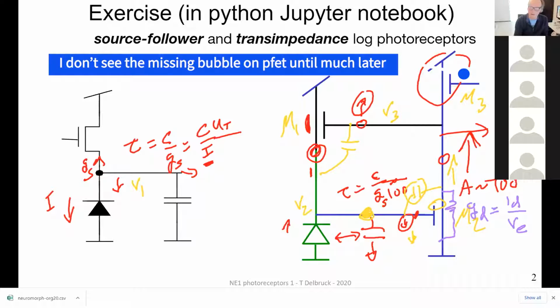I can. Okay. So you have a perfect current source on the top right, IB, right? That's an ideal current source. It just sources IB, period. In order to turn these 2 transistors into a voltage amplifier, the bottom transistor must have a finite drain conductance, GD. And GD is determined by the early effect to be ID over the early voltage. It's a current divided by the early voltage.